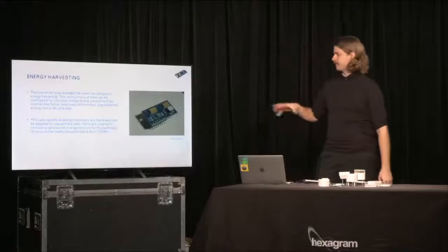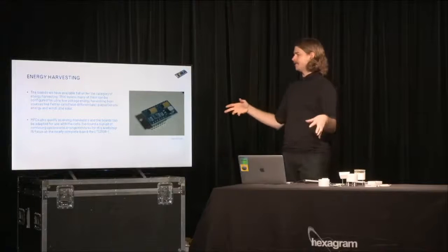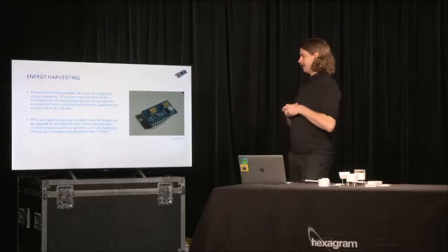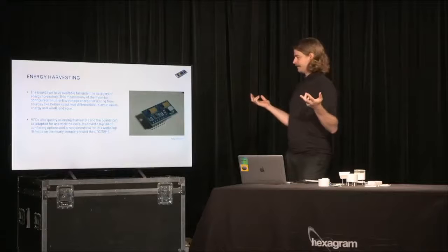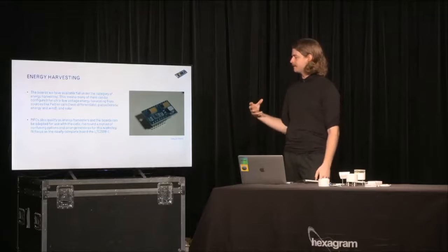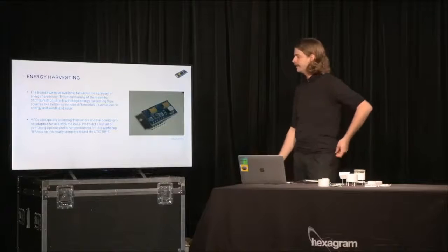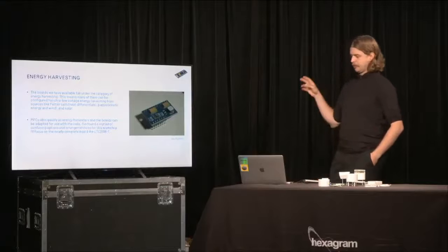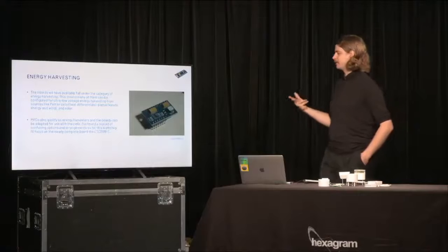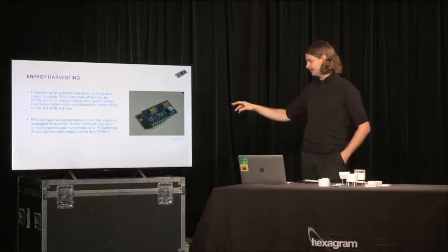These chips are meant for energy harvesting, which is what microbial fuel cells do. Energy harvesting is just using residual energy from the environment. So wind, solar, heat differentials, and in this case, soil ions. And it's usually very low voltage. This one's considered ultra low because it's so small. You need to use special boards, but they're very hard to find. There were a lot of boards that came out in like 2014-ish and they disappeared. This one's still available, super cheap. It was like $8.